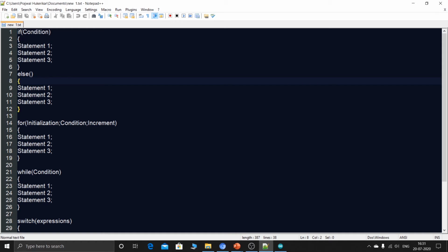So I can write that if, and again I'll have to use a variable to store the data that is read by the analog read function. So I just consider var, that is short for variable. So var is greater than 500, and then in the statements I'll just write digital write, and in brackets I'll write the pin number of that LED, that is 3 comma high, and in the else statement I'll write digital write, in brackets 3 comma low. Okay, so this is very easy, and again this statement is not limited to Arduino programming, it is used everywhere like C or Python and stuff.